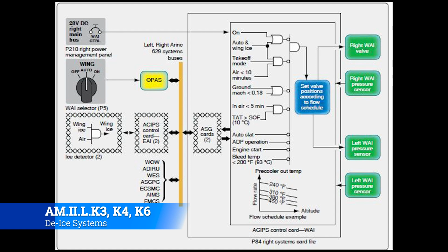That basically means that the engine's not producing enough heat anyways, and so it's going to shut the bleed air valve and keep all that heat inside the engine, rather than trying to pipe it out where it's not going to do any good anyways. But those are different systems. There are different ways that you can see the wing anti-ice system just turn off.